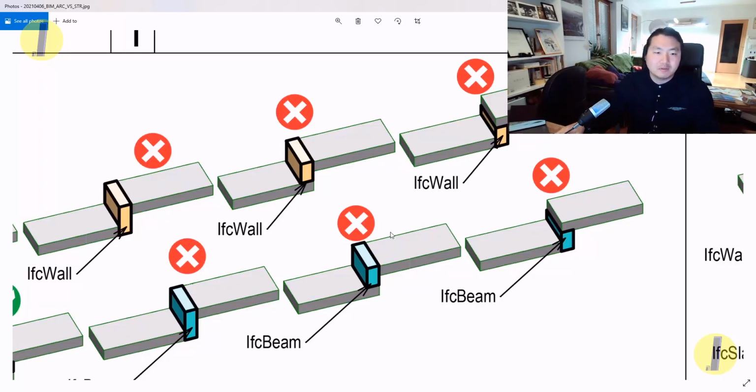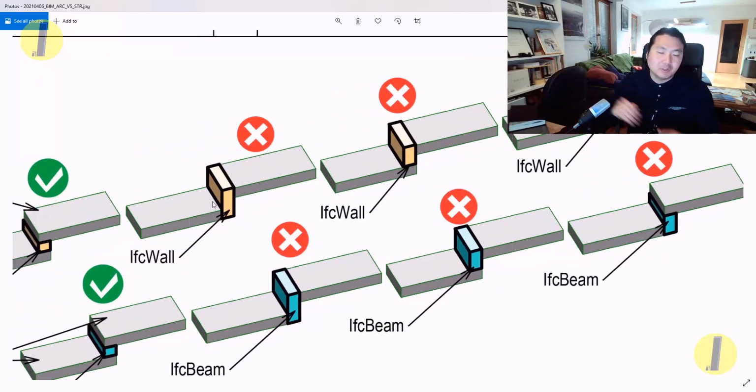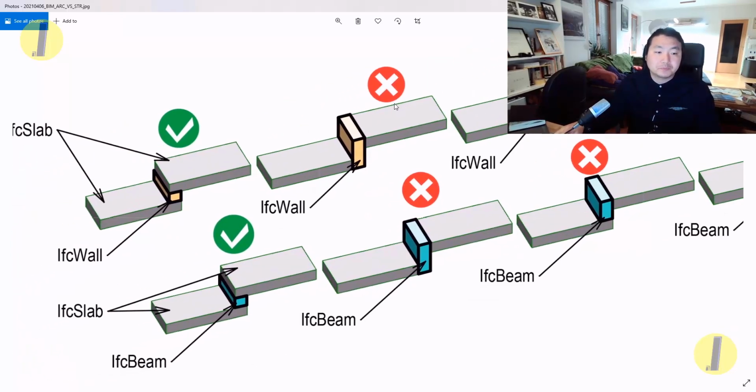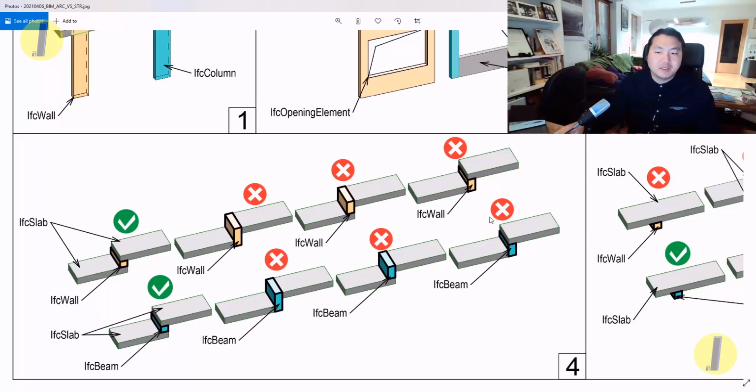If it's more than 1.5 meters, we should consider that as another building story, especially when the floor area is bigger than 30 square meters. In that case, you have to think about what method is best to get your quantity takeoff as well as structural analysis with reinforcement. So this point we have to discuss well.